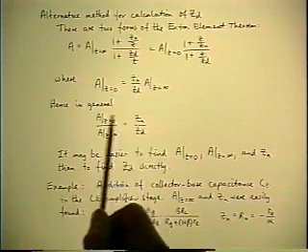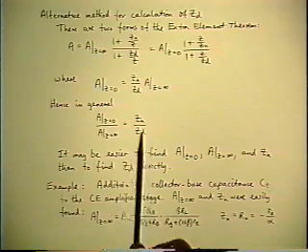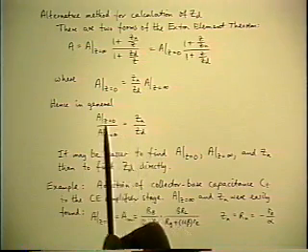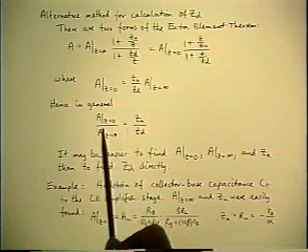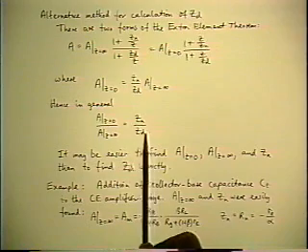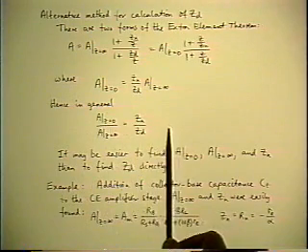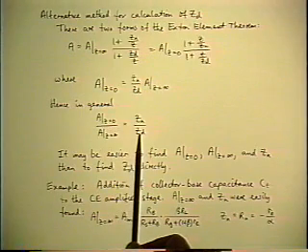And then you can find Zd from this ratio relationship, which would be easy to do because it's only products and quotients involved. So even if you have factored pole zero forms for all of these, which is desirable anyway, to calculate Zd from the other three simply involves products and quotients of the poles and zeros, and there's no cross-multiplying and refactoring to do. So it would be an easy process also.